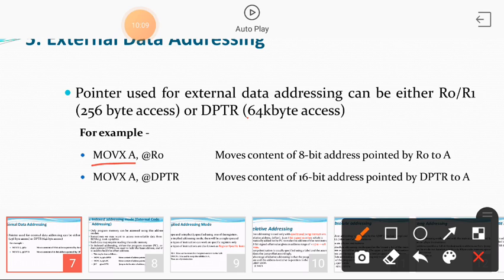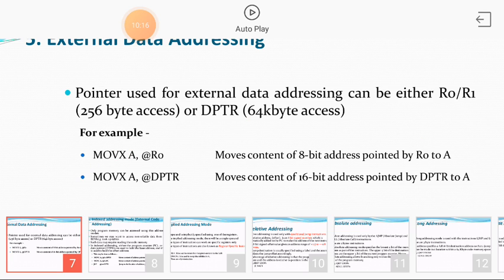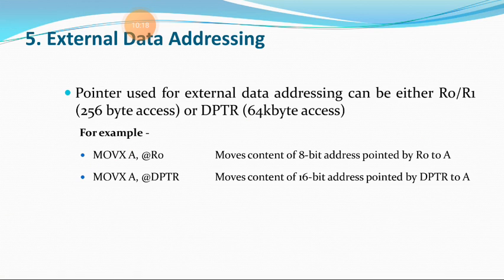X indicates it is an external memory operation or data operation. And here, MOVX A, @R0: move the content of the 8-bit address pointed by R0 to A.